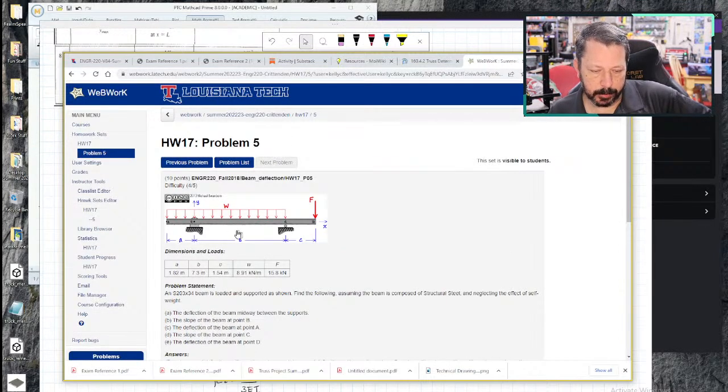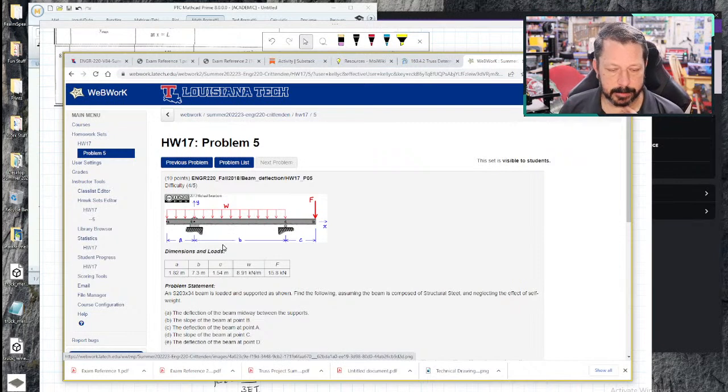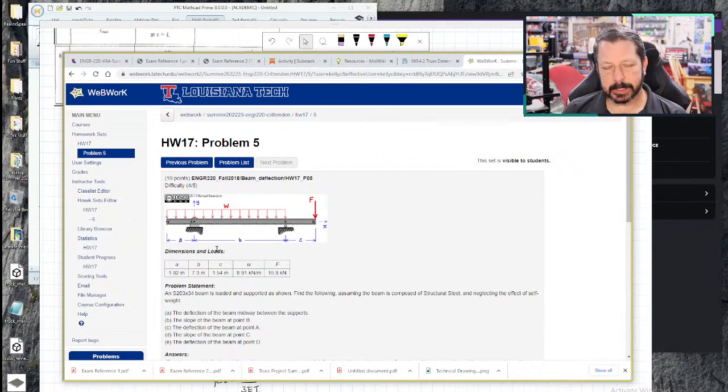This one is just a little more complicated because you've got to divide this distributed load. Same kind of thing as we did first, where you take the point load and move it to a moment. You take the lumped version of this little piece of the distributed load and create a moment about B. So there's a lot of little pieces going on in this one. This one's a little beyond a test question.